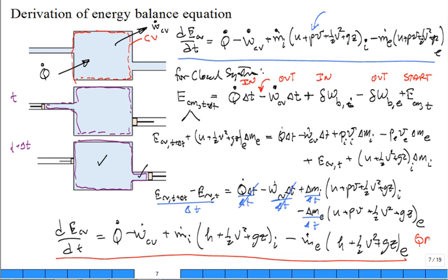That's what we set out to derive. Is it the same as what we said we were going to derive? The equation's not that hard. I think the derivation's a little tricky because you're going from a control mass to an open system control volume analysis. And the big surprise is why you get enthalpy. A lot of students say, I think that should be a u only, professor. No, it's u plus Pv. Where did that Pv come from? From the boundary work associated with pushing fluid into the control volume and having it push its way out of the control volume.